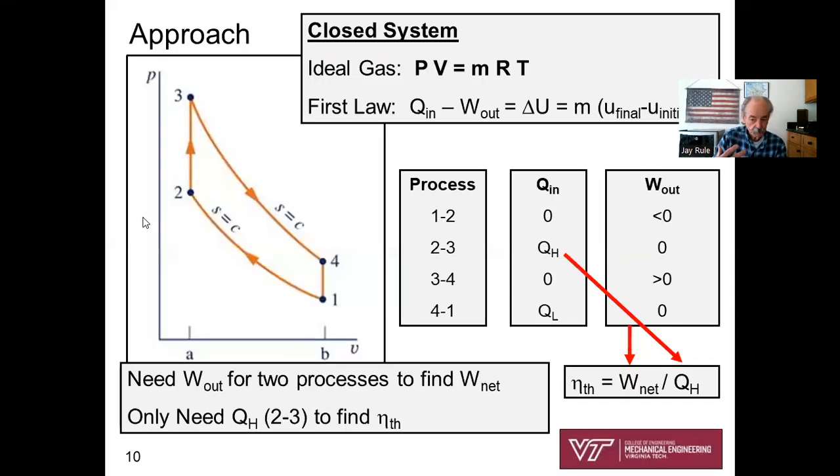All right. Start with a sketch. So I'm going to repeat the sketch of the Otto cycle. So we're starting at point 1. Let's plan our work a little bit. What kind of things will we use to analyze this cycle that involves air? We're going to use the ideal gas equation of state, PV equals mRT, over and over.